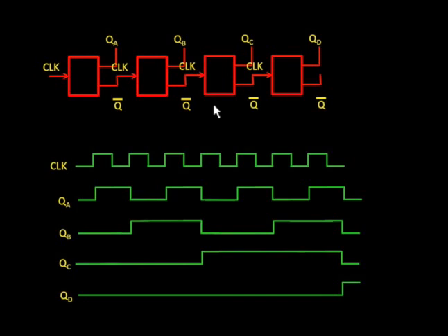Here is a counter with 4 flip-flops. It is a 4-bit counter. It can count up to a 4-bit word. Let's evaluate the count at various points in time. Each flip-flop represents a digit. A high state represents 1, a low state represents 0. A vertical line tells us the status of each flip-flop or bit at that stage in the count.